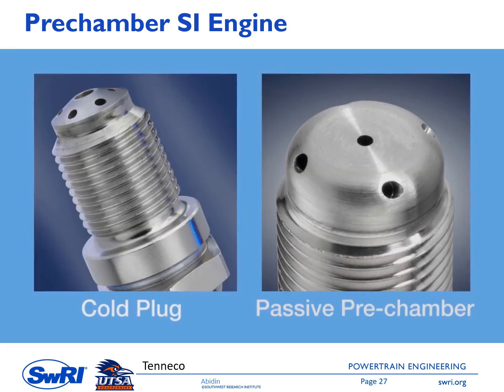This feature is a pre-chamber spark plug. It is a passive pre-chamber, so we don't have fuel introduction to this pre-chamber. And this is a product of Tenneco. I think you can also buy this pre-chamber spark plug, and you can try it in your car to see whether you get improvement or not.